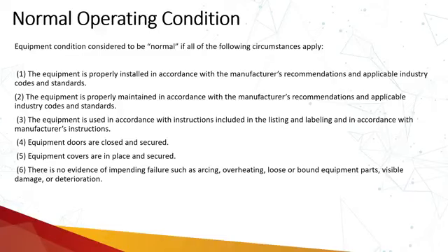For example, if there is a puncture in a tire, that puncture is basically the impending failure or the potential failure. With a punctured tire, you can go 1 kilometer, 5 kilometers, 10 kilometers, or that puncture might be so severe that you cannot drive your car 1 inch. In that case, when you are not able to drive your car any further, that potential failure has converted into the functional failure of the equipment, that now you cannot perform the function for which the equipment was actually used.